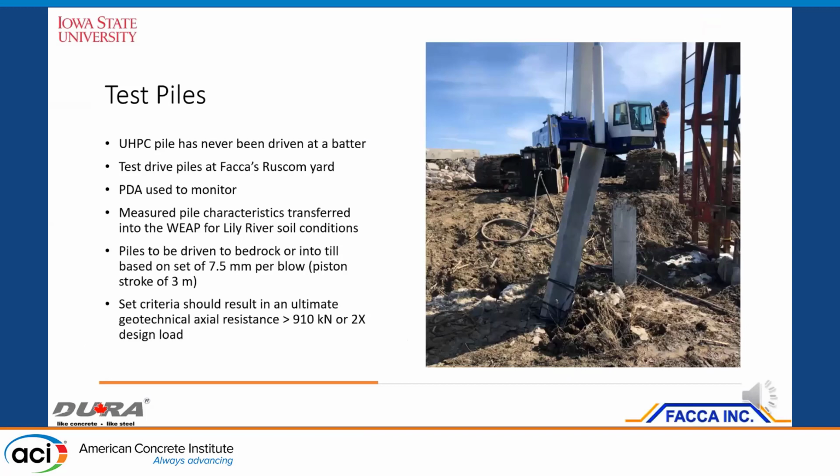The only snag here is that none of these UHPC piles has been driven at a batter. One of them is 1 in 4, another 1 in 10. So we decided to try it out at our yard before we go out to the actual site to drive it.